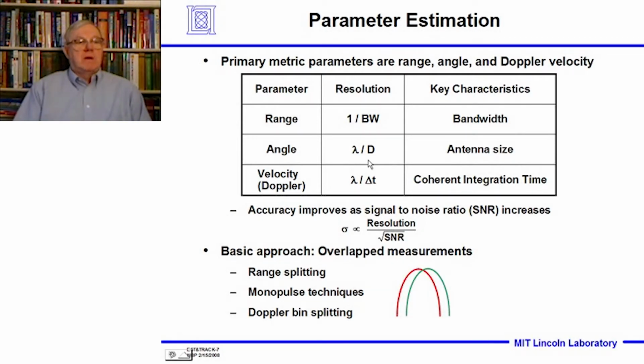And each of these resolutions, the accuracy improves significantly as we increase the signal-to-noise ratio. And the accuracy is proportional to the resolution, quantity up here, divided by the square root of the signal-to-noise ratio. And that would be in natural units, not in dB.